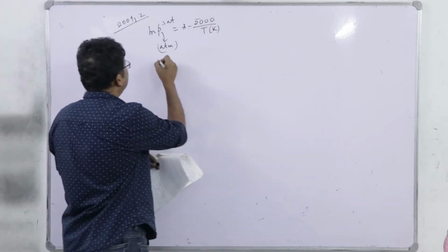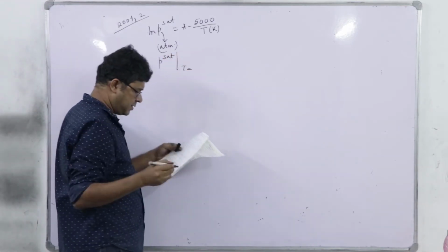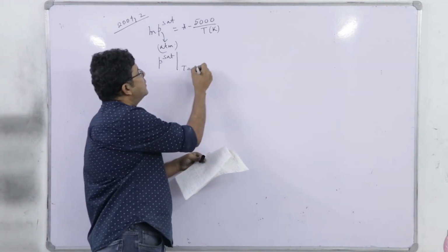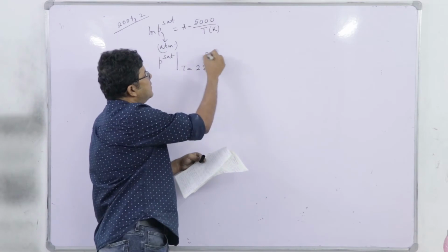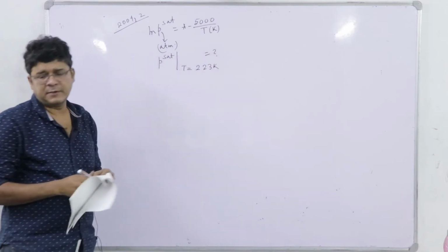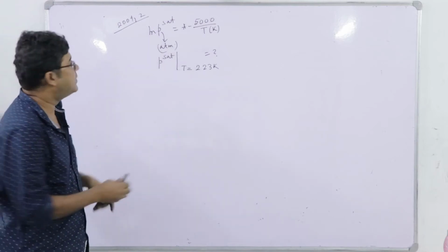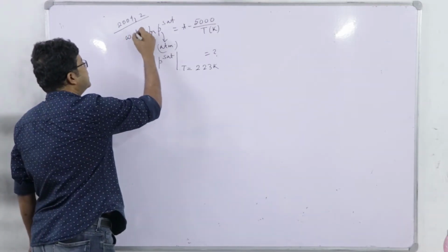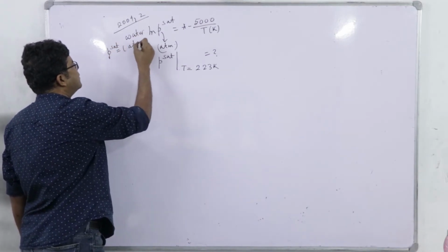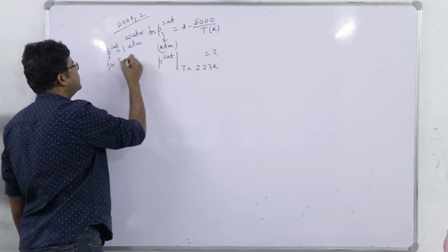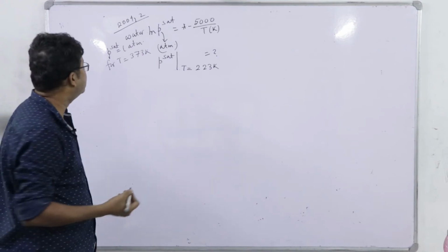So we have to find out the vapor pressure at T equal to 50 degrees Celsius, so this 323 Kelvin. So basically the problem reduces to finding the value of A, but we have to note that this is water, and for water Psat is equal to 1 atmosphere for T equal to 373 Kelvin, because it's the boiling point, right.